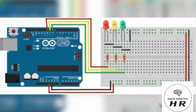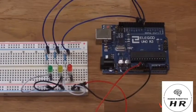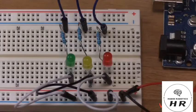So you'll need to set up your red, yellow, and green LEDs on your breadboard, and they are going to pins 10, 9, and 8 of the Arduino respectively. However, between the pins and the long legs of the LEDs, you want to put a 220 ohm resistor each. Also, you want to attach the 5 volt and ground pins of your Arduino to the live and ground rails on your breadboard. If this seems a little confusing from the video, head to the MakeUseOf website where there is a Fritzing diagram of this. There'll be a link in the description to the article in question.